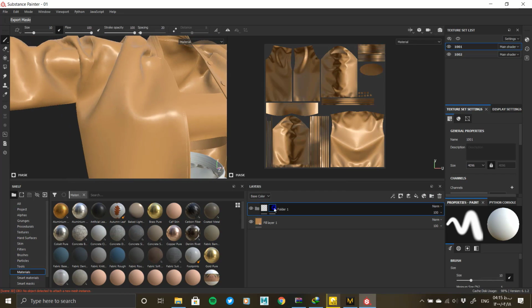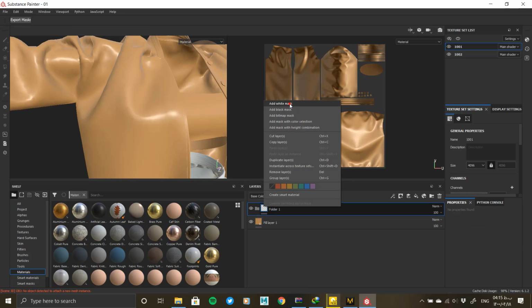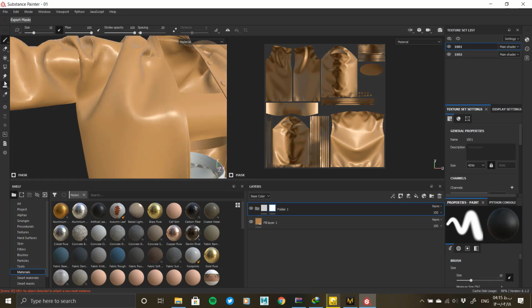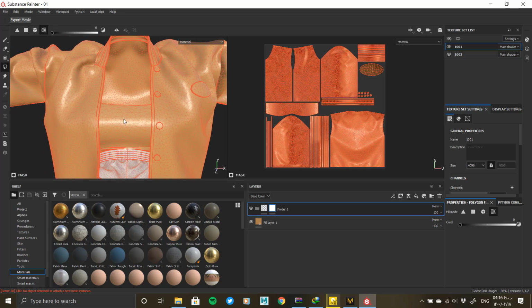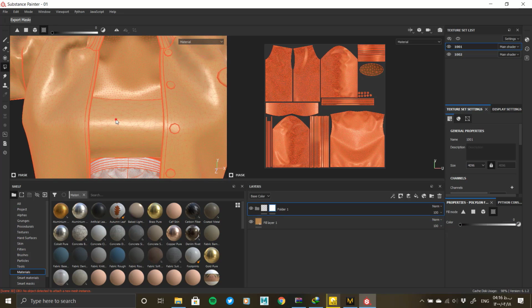There is another type of this detail called the smart mask, which cleverly creates a series of details and irregularities based on bake maps. Using these items is very useful in some situations, but it is not good to overdo it. Using generators is also very useful. Generators such as dirt and fiber, automatic stitches, and UV borders are very useful, and are used in many projects. You can also use the smart materials in the software itself, and change it to your desired material by turning off and on the layers, and changing them.